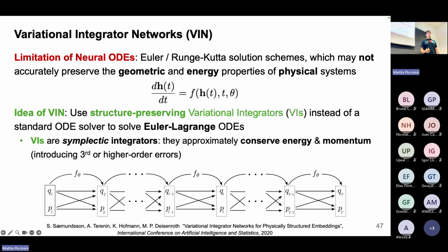Okay, so there are particular types of variational integrators already available in the literature. You just need to find the best one that suits your application. And this can really help preserve energy better than Runge-Kutta or Euler. And so this is simply what the integrator does at the end, right?